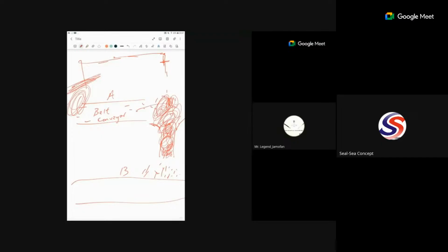So the process guy will compulsorily have to come to this unit, declog the chute, and make sure the chute is free. When it becomes free, they tell the control room, they power up again, and the system continues running.